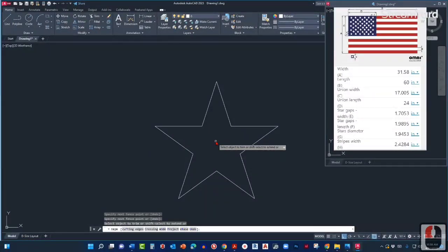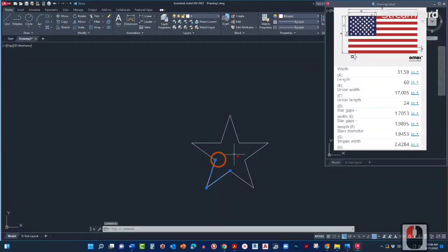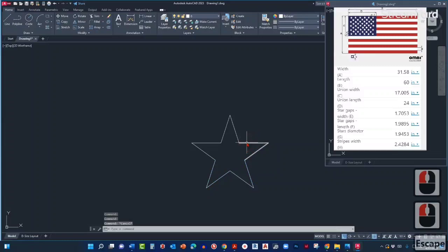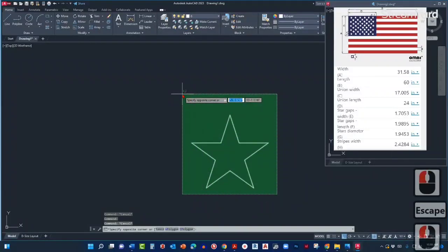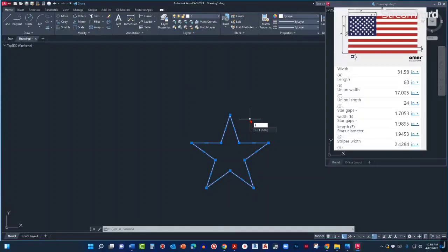And then I'm gonna press escape. Okay, so our line is almost ready, but I can see that some of these objects are divided. So in order to combine all of these in one single polyline, let's simply select all of the objects for our star, like so, and let's use another command called join. Join, the shortcut is J. And we press enter. You can see that over here, 9 segments joined into one polyline, which is nice.